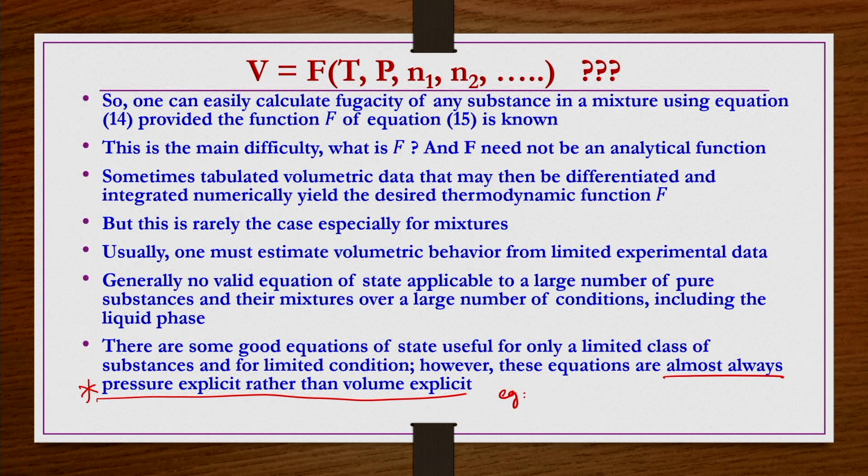As I was mentioning, the Redlich-Kwong equation, if you see, you can write it in a pressure explicit form. But you cannot write it in a volume explicit form. So, because of this reason, for the Redlich-Kwong equation we cannot use equation number 14. This is one example, there may be many other cases also.